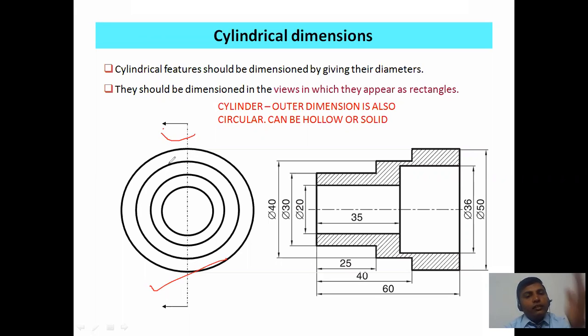If I cut this particular hollow shaft, you can see this is the way the cutting plane can be shown, and this is the way of showing the hatching lines. Hatching lines are always parallel to each other, the distance between the hatching lines is 1 to 3 mm, and they are always inclined to the baseline at 45 degrees. Again, this is a chain and parallel combined dimensioning, with the aligned dimensioning system used.